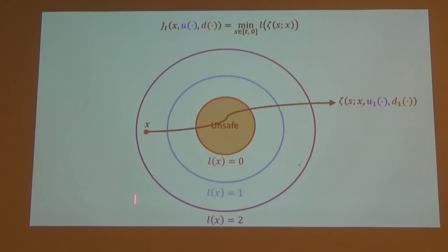So we start from roughly like 1.8 L. Then our L decreases, and it becomes negative once it hits the unsafe region. Then it exits the unsafe region and again starts increasing, probably to something like 2.5 or 3 at the end of the trajectory. The minimum over this entire trajectory is achieved when the trajectory was passing through the unsafe state. In particular, the value of this cost function for this trajectory would be negative.